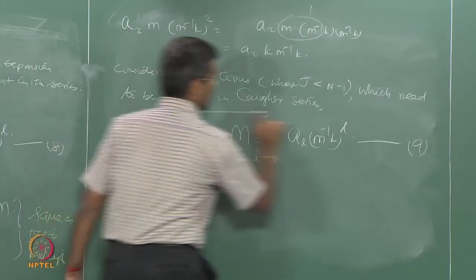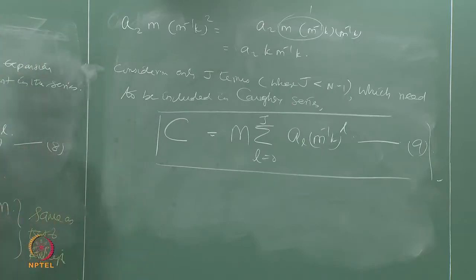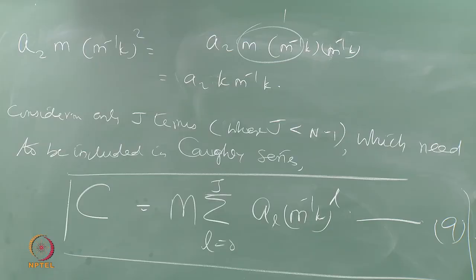That is my damping matrix. Actually need to check the zeta value in every mode, that they should be uniformly distributed. We are talking about the whole argument on classical damping applied to the structural systems.